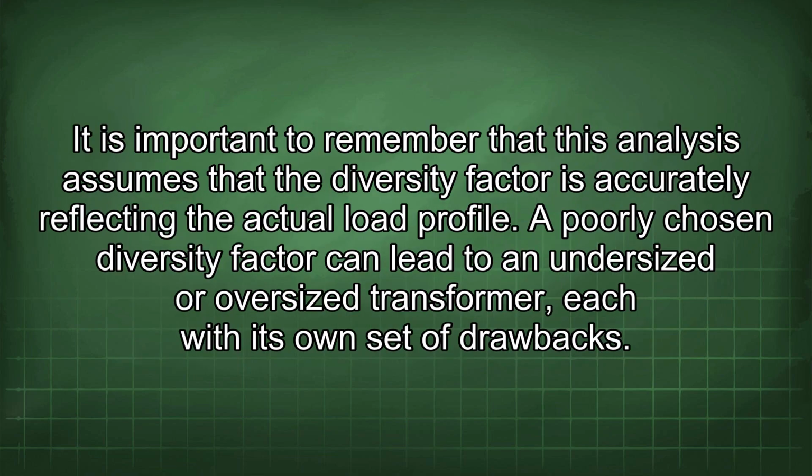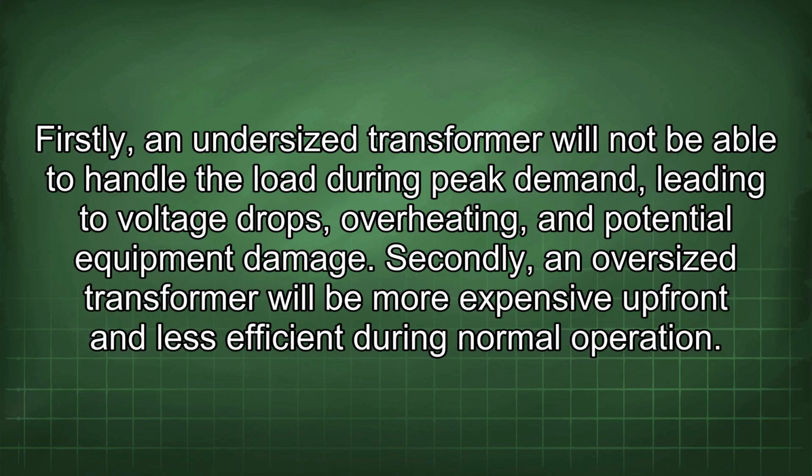It is important to remember that this analysis assumes that the diversity factor is accurately reflecting the actual load profile. A poorly chosen diversity factor can lead to an undersized or oversized transformer, each with its own set of drawbacks. Firstly, an undersized transformer will not be able to handle the load during peak demand, leading to voltage drops, overheating, and potential equipment damage. Secondly, an oversized transformer will be more expensive upfront and less efficient during normal operation.